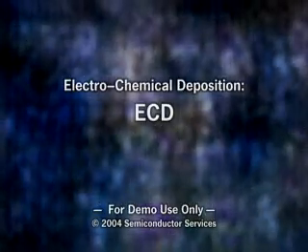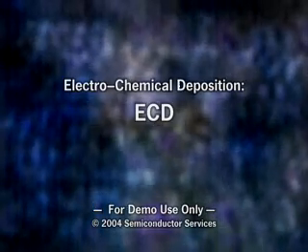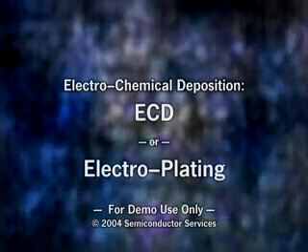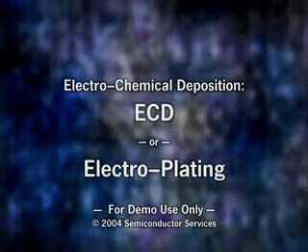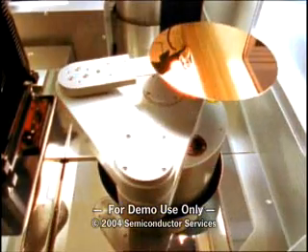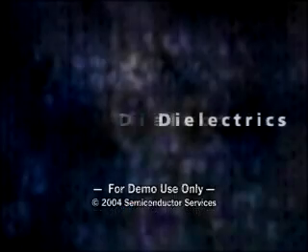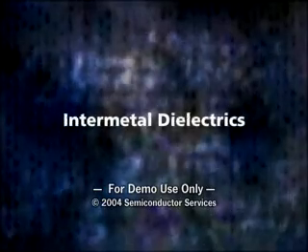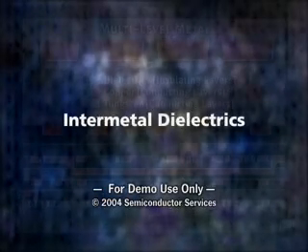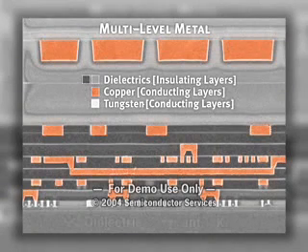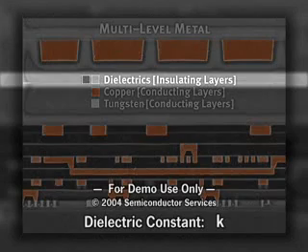Another method of depositing a metal on the wafer is electrochemical deposition, ECD, also referred to as electroplating. An important use of ECD is to deposit copper layers. An important issue in the multi-level wiring structure is the dielectric constant, called K, of the material used for the insulating layers.